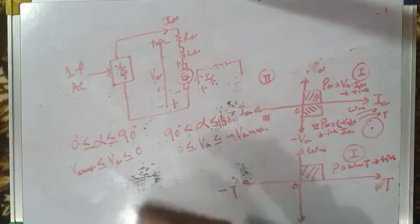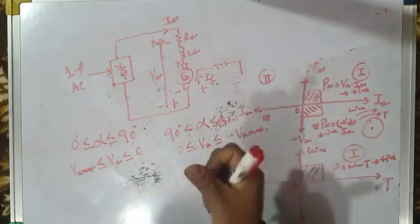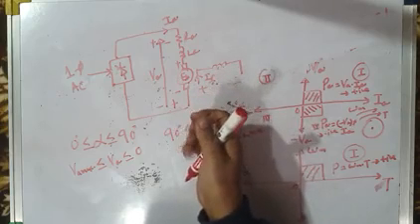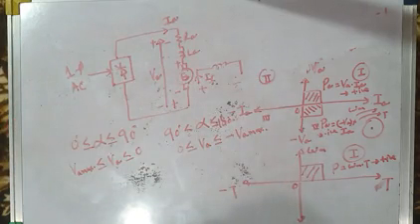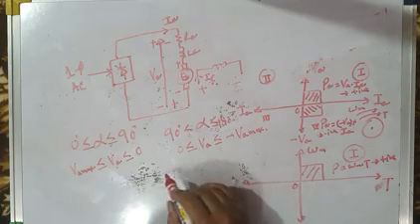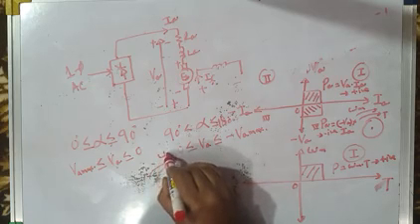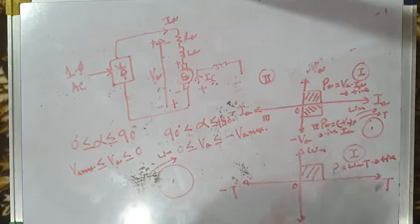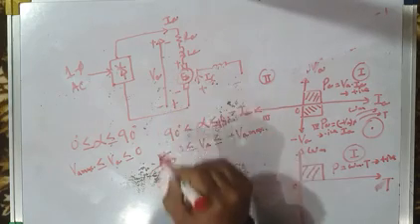It is converting the inertia or kinetic energy of its rotating parts into electrical energy. In other words, it is taking the mechanical energy of rotating parts, converting that into electrical energy, and supplying that electrical energy back to the source. So isn't it the regeneration mode? Yes, it's the regeneration mode. And in the regeneration mode, if the speed of motor was previously in this direction, what is torque? Power is becoming negative. Negative power means the motor is operating as a generator.